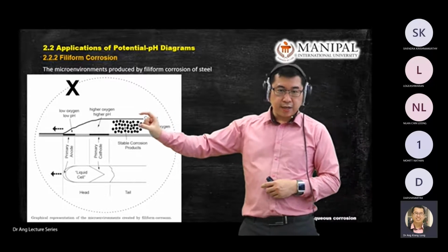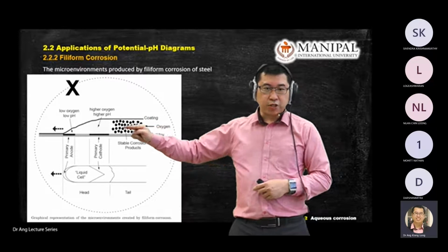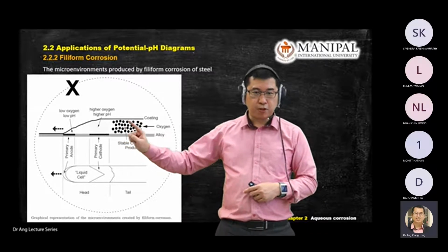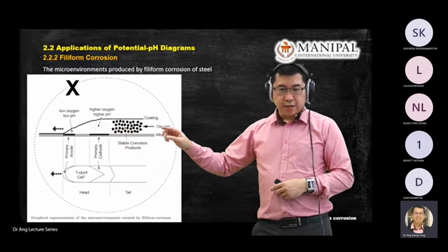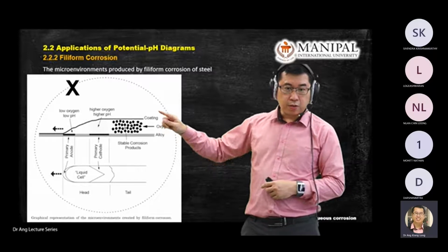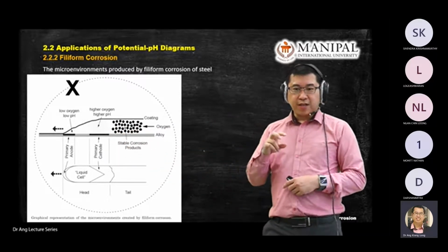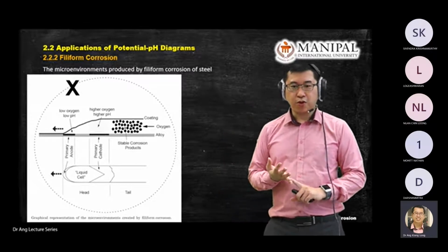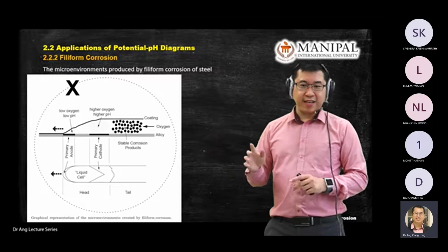And here it will become like a tunnel for the corrosion to get oxygen in. Because this is like a tunnel already, there's a space here. So when you have space and you have the porous product and a hole here, as your head advances, you will have oxygen coming in from the back. Imagine this is the opening of the corrosion. The oxygen will go in through the space of all these products and supply oxygen to make the corrosion even faster. So you know that corrosion can happen with water, H2O, hydrogen, and oxygen, plus the metal. And if you add lower pH or an acidic solution, then it becomes faster and faster.